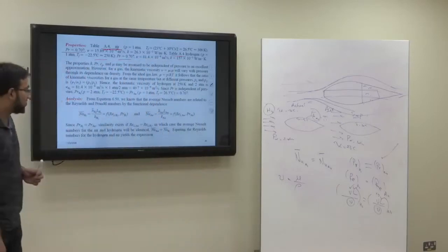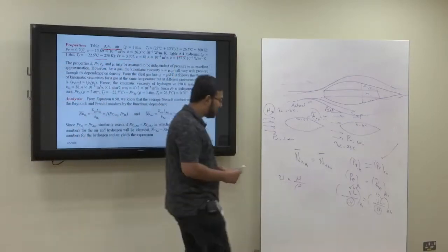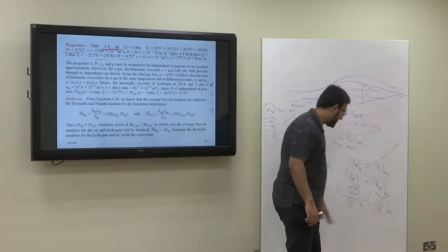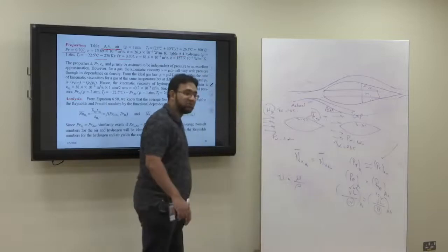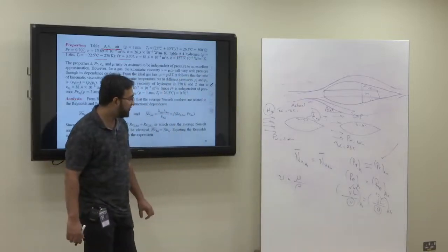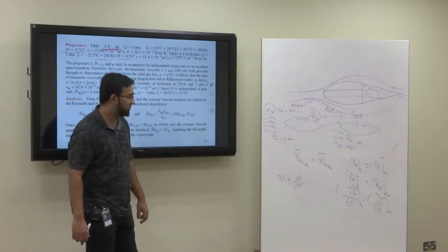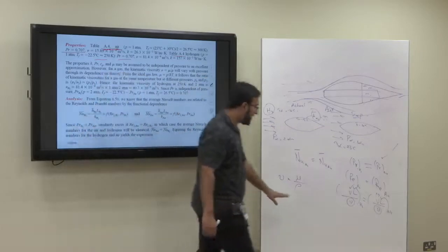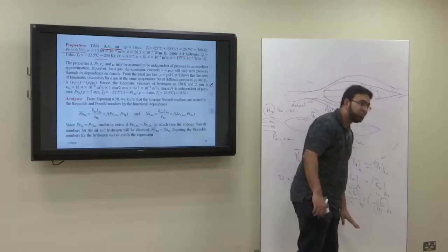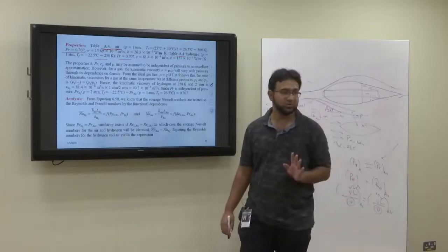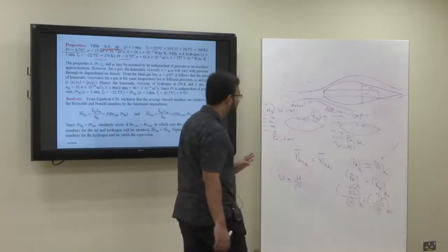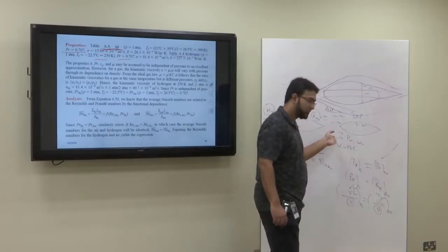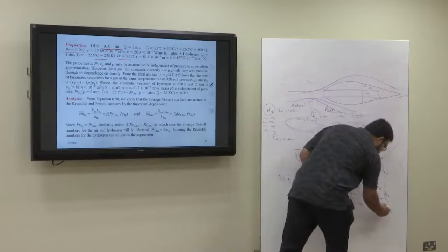Okay. So when we want to find out this kinematic viscosity, we have to consider the pressure. Now the values for hydrogen and for air are both given at 1 atmosphere pressure. For the case of air, it is not a big issue because it is already at 1 atmosphere, so we can directly use the same value.